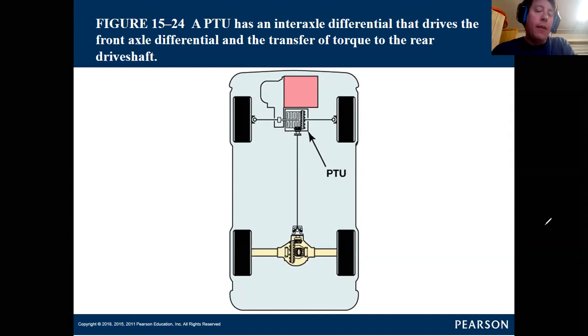There's a little bit of give because it's friction, it's fluid, it's paper disc, metal disc, and oil. And you're not going to get a violent lock. You're going to get a little slip in a worst case scenario, which will cushion that engagement and not freak out the driver of the vehicle. If you have one of these vehicles and you haven't experienced it yet, give it a try. It's not fun. All right, let me get this off of here. Let's move on. We're getting close to the end.